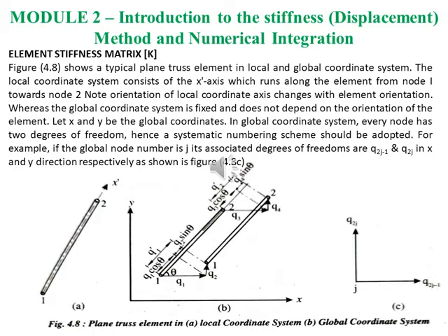So here you can see a simple plane truss element. Then I am taking it to the local coordinate system, giving it the angular value of theta, then finding out the cos and sin values of this element to represent in the x-axis and y-axis.